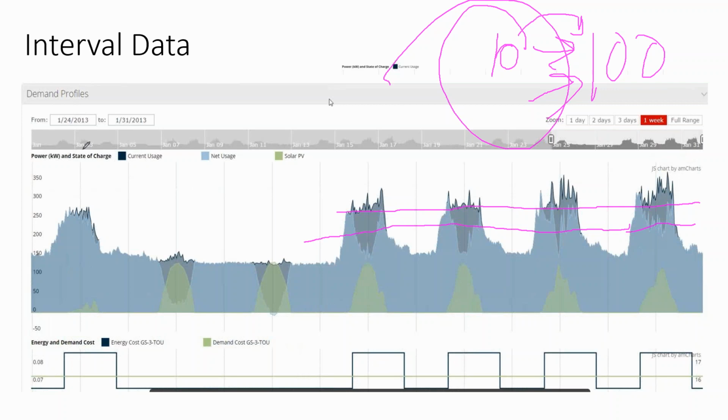Dip your toe in the water, and actually demonstrate to the client with a smaller system that the battery load leveling model works. And perhaps that means that today you don't need a battery that will last for 30 years or 15 years. Maybe you only need a battery that lasts for 5 years. And we'll see what lithium ion looks like 5 years from now, but we might use a less efficient system today. And some of the infrastructure you put in is going to be reused. The battery inverter, the charge controllers, the solar array will keep clicking along.